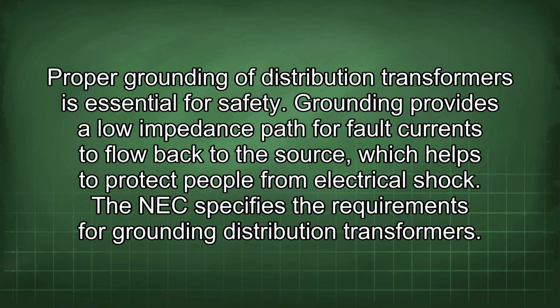Proper grounding of distribution transformers is essential for safety. Grounding provides a low impedance path for fault currents to flow back to the source, which helps to protect people from electrical shock. The NEC specifies the requirements for grounding distribution transformers.